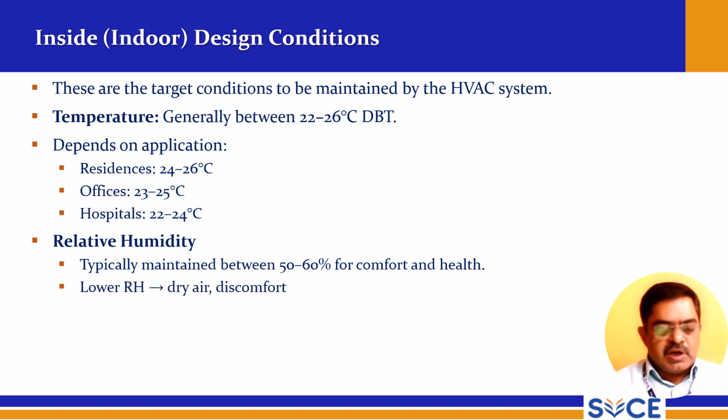If it becomes lower, the air becomes dry and causes discomfort to humans. With higher relative humidity, there is mold growth and poor IAQ, so internal air quality will be very poor in this case.